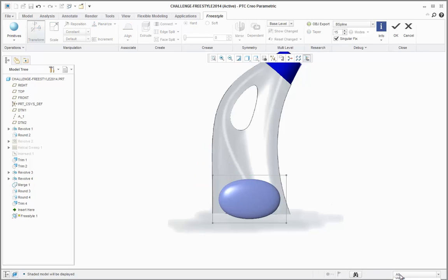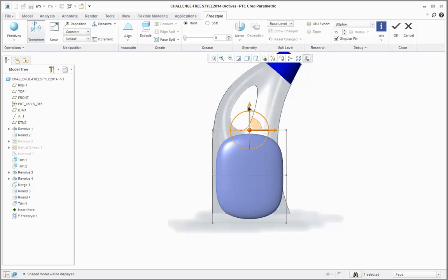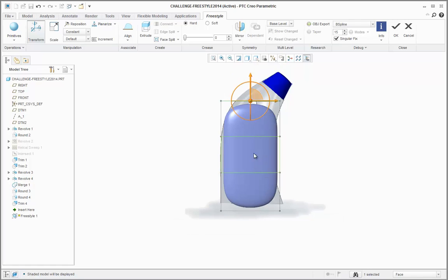I now need to add more control to the mesh. I do this by extruding or subdividing the mesh. Change the selection filter to face and box select the top face of the sphere. Holding down Alt and dragging will extrude the control mesh to add more elements. Repeat this to position the control mesh close to the hole.